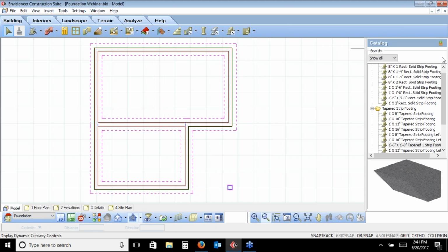And it's going to break it down and step down the wall in maximum of 1 foot increments as it goes down. So when I click OK here, and I'm just going to zoom out a little bit so we can see it, you can see how it's stepping down so it can go down that additional 4 feet. That stepped down the wall. The footing itself is still the same.